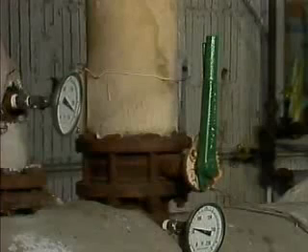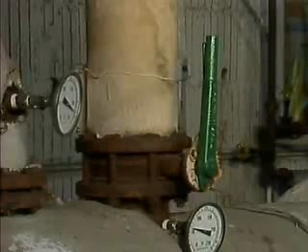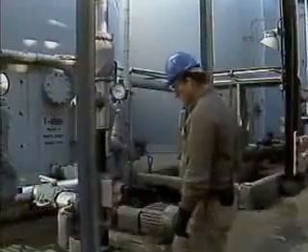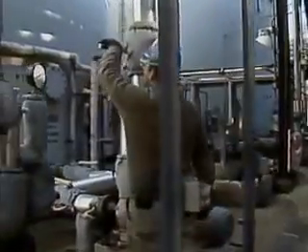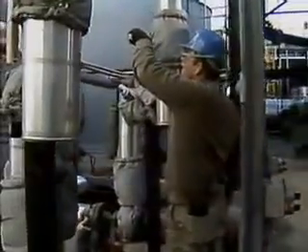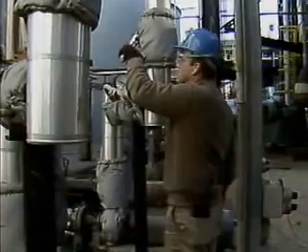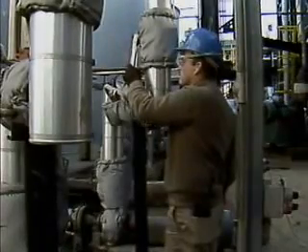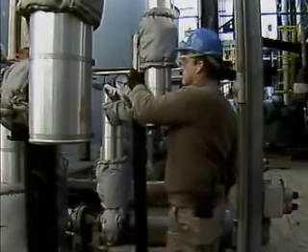The rate of fluid flow through a butterfly valve is adjusted by using the handle to change the angle of the disc. The handle is a lever that may include a spring-loaded locking device. To change the position of the valve's disc, compress the lever and turn the disc to the desired position.